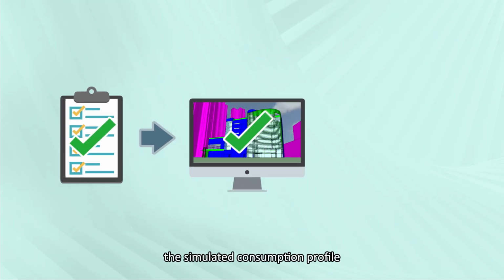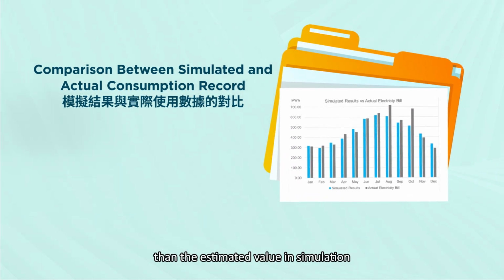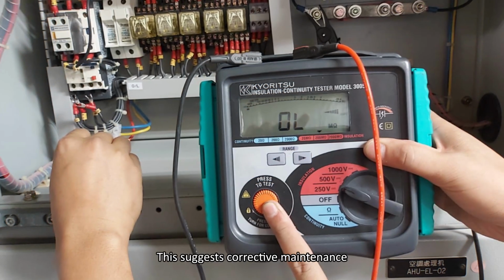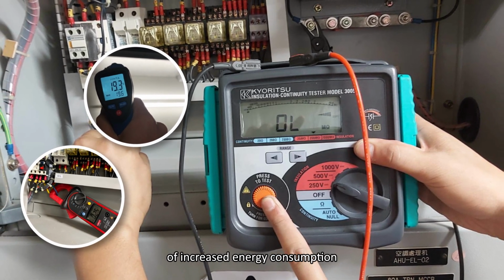The simulated consumption profile shall have no big difference with the actual utility bill. If the utility bill record is way higher than the estimated value in simulation, it is very likely that there are equipment malfunctions or control signal faults. This suggests corrective maintenance and functionality review is required to identify the root cause of increased energy consumption.